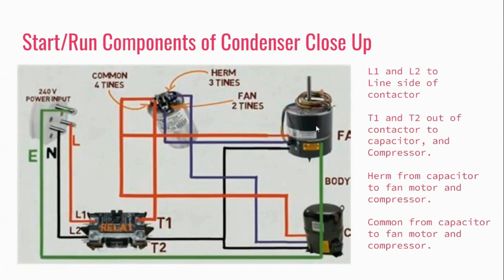This is not showing it correctly, but each one of these is grounded. Each one of these components is grounded, except for obviously your capacitor is not grounded. That would not be good. So the reason why you can't just pull a capacitor out is because it stores electricity. So if you just grab that and pull it out, it's going to zap you. You're going to get a little shocky shock. And it's actually not that small. It's actually quite painful. I've done it.